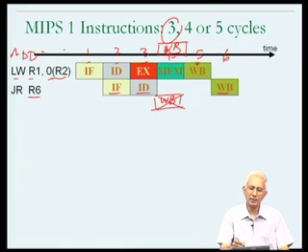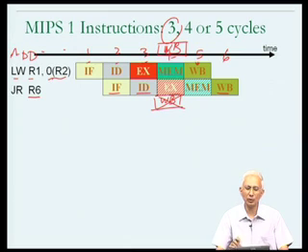So once again, during cycles number 4 and 5, no useful activity as far as the jump register instruction is taking place. What I will do is just assume that the EX hardware and the MEM hardware, in this hashed mode, are passed through, or not being used for the execution of the steps of the instruction, but are in some sense being occupied by the jump register instruction in cycle 4 and cycle number 5, prior to the write back hardware being used in cycle number 6.